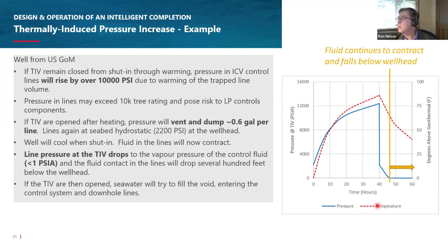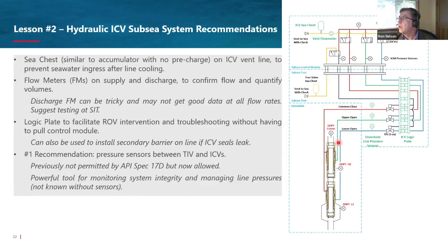And if I then open up those TIV again, seawater will try and enter the control lines. It'll contaminate my control pod, and it'll contaminate my downhole lines. So this is a very, very impactful situation that you definitely want to work through here. Make sure this doesn't happen to you. And there are a few ways you can manage this. There are some modifications you can make to your subsea tree that I'll suggest here.